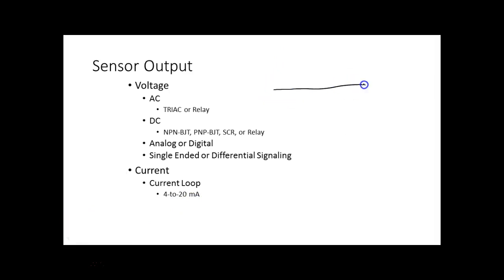They decided not to use common. So what do we need to make current flow? We always have to have a difference in potential. Does that make sense? So if I send in digital information over here, and this could be analog too, but digital is easier to see, what they would do is use one conductor, and they call it the plus, not because it is a positive signal, but because it's what we call the non-inverting signal. And then on your other wire, they'd send the mirror image of this.